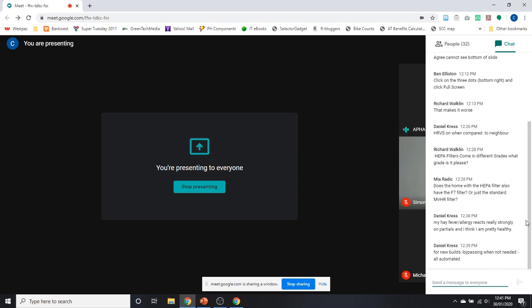Next question, does the home with the HEPA filter also have the F7 filter or just the standard MVHR filter? If you're there still, Harley, you're welcome to put that comment in. Sure, yep. So I've got my normal F7 filter, and then the HEPA filter is added afterwards, downstream. So just as Joel drew on his diagram, I've got the outside air hitting the normal Zender F7 filter, then going through the Zender HRV, and then on the output, it goes through my homemade bucket HEPA filter, and then it goes into the manifold and then into the rooms.